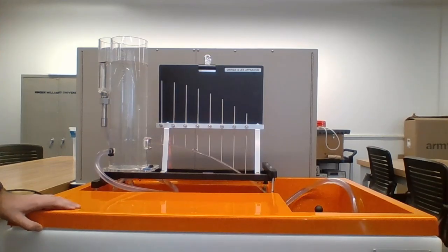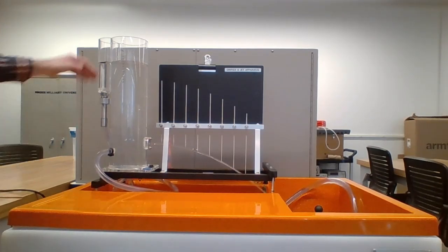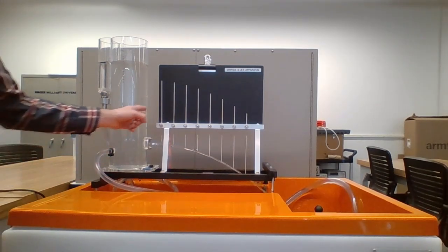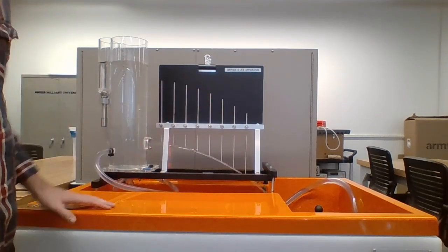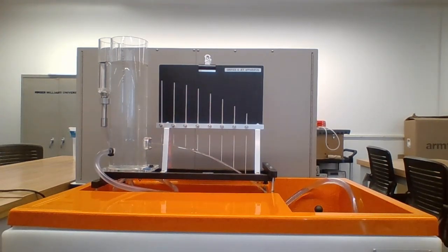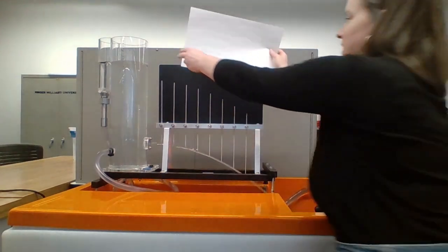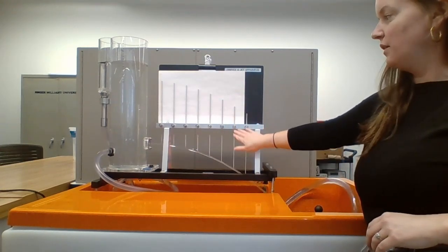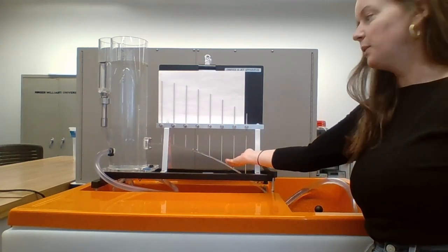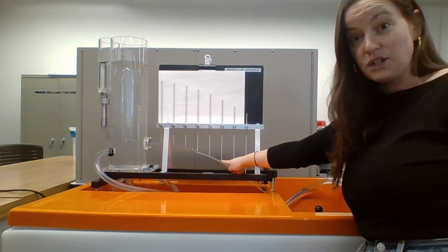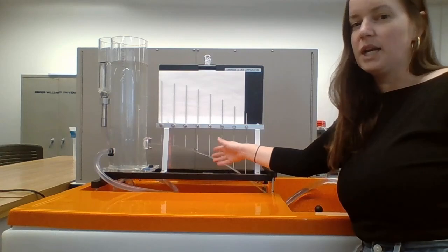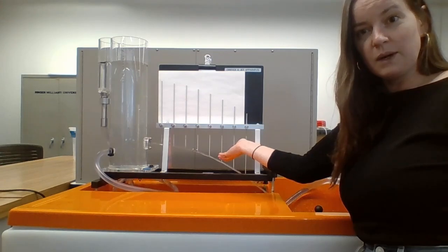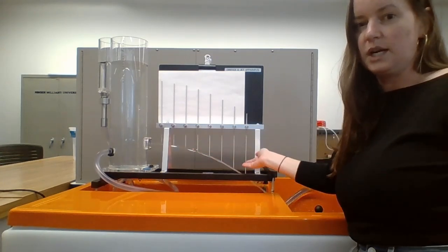So the next step after we get our constant head tank set up correctly is to take our measurements with these needles. So Maya's going to do that. Great. All right. So in order to do this, we're going to place this sheet of paper. Hopefully you can still see all of these needles. It may be hard to see in your view, but right now these needles down here are actually touching the water, and so they're disrupting the flow, which changes all of the physics. So we want to move these needles so that they're just above where that flow is. We don't want them changing what this projectile motion is like.